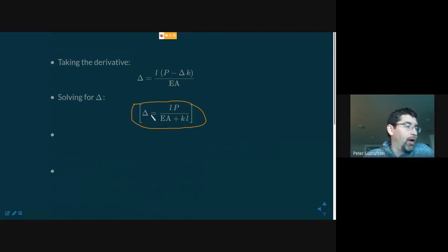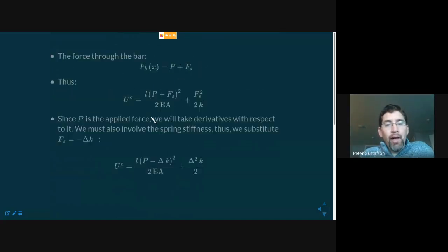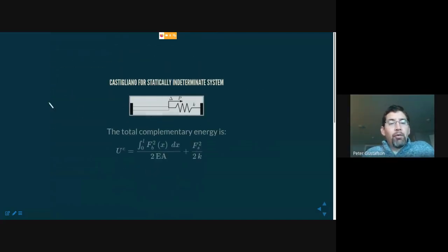Nicole had volunteered one. Thanks, Nicole. So you said would displacements at the end be 0 because it's cantilevered? So we've got to be a little careful with the use of that word cantilevered. Cantilevered really refers mostly to beam bending problems and the boundary conditions associated with bending. That is, the displacement at one end is 0, the slope at that same end is 0. I'm not sure which end you're referring to in your comment in the chat window.